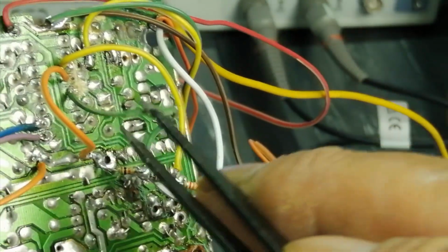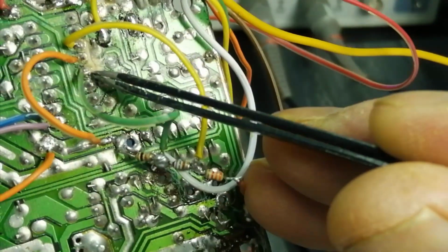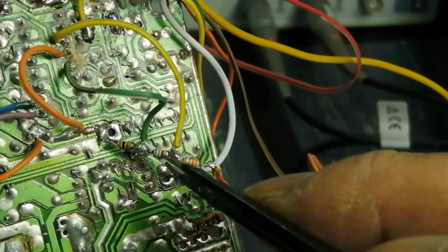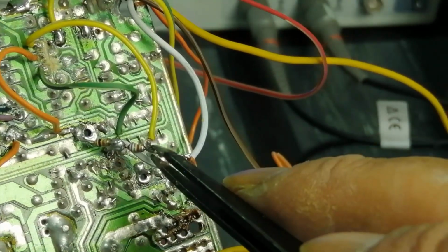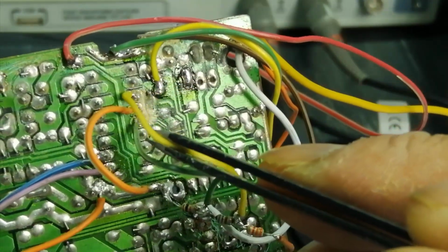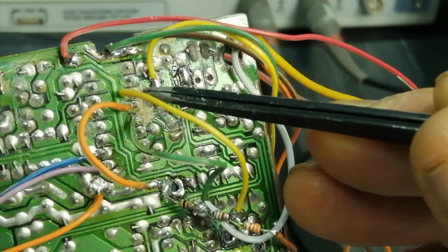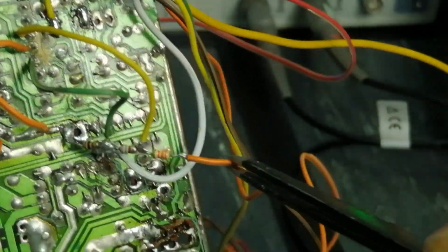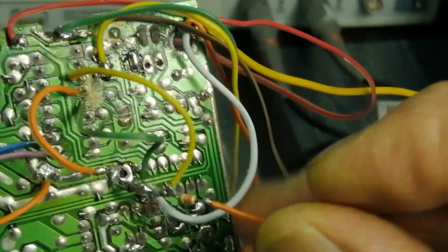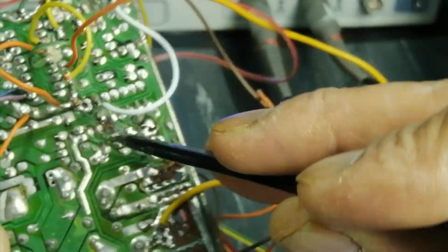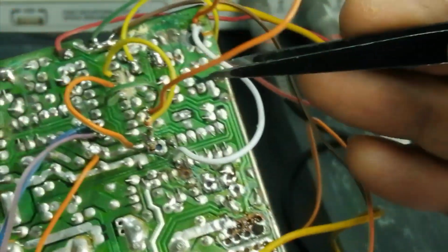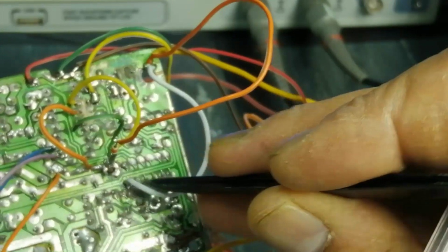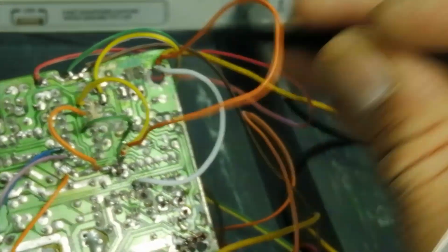After the 1k resistor I got 4 volt and connected it to pin number 5, that is the 12 volt input. And after the 680 ohm I got 3.3 volt and connected it to pin number 3. So I connected 3.3, 5 and 4 volt at pins 3, 4, 5, and the last end of the 3.3k resistor I connected to ground. The PS on command here, green wire, is connected directly to ground, so no need to install a jumper. I connected it here locally. Now this power supply will go directly into power on state.